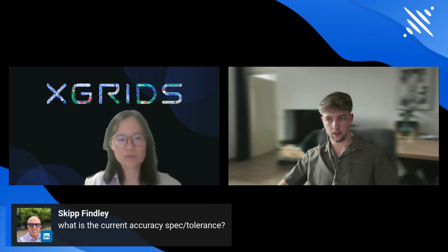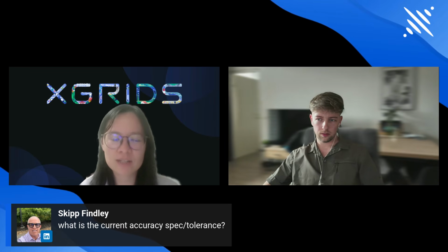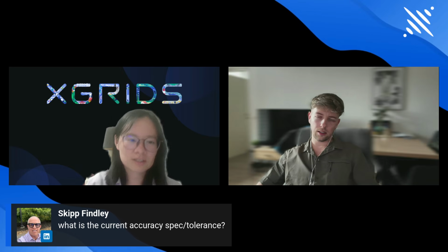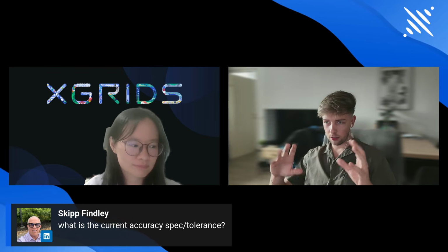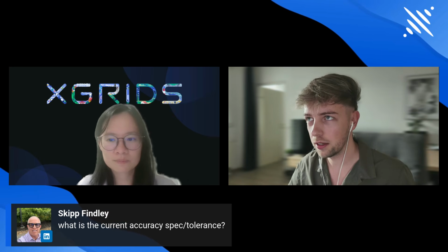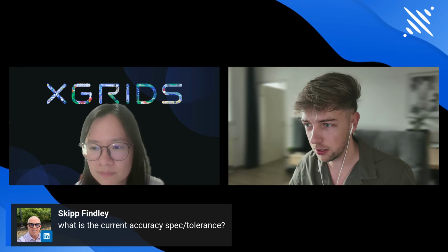I think it's also a very important question for the scan to BIM projects, and you can also tell it a general requirement. It depends on the environment, how the lighting conditions are, how big the scale is, how complex the geometry is. But in most cases, for most projects, let's say 1,000 square meters, you have 1 to 2 centimeter difference at max.